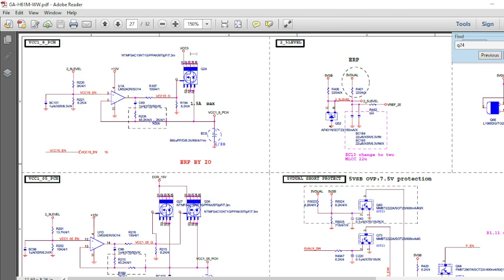But in this motherboard, 1.5 volt means DDR3 RAM is connected, that's why we cannot give 1.5 volt as an input, because we need 1.8 at the output. So that's why they have again given 3.3 volt through this Q24, which is the MOSFET you will find near the PCH, and at the output you have to get 1.8 volt. For this MOSFET to work they have given the LM324.